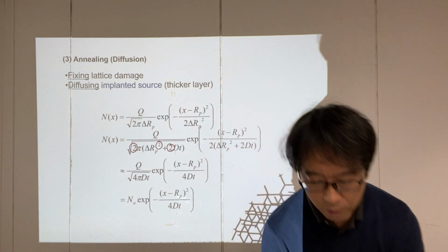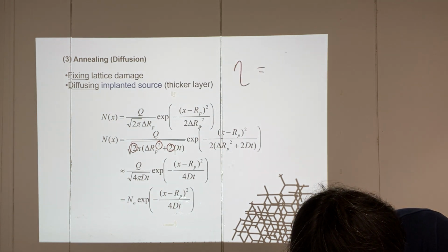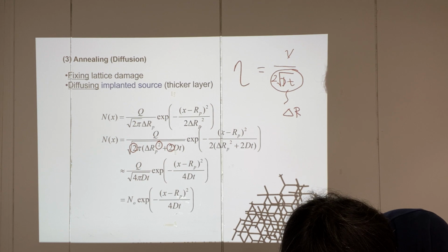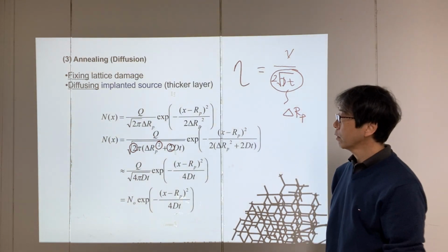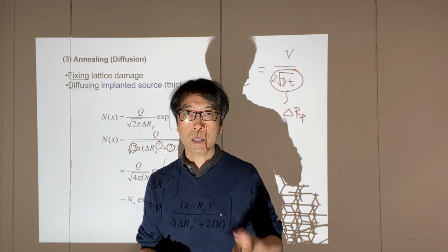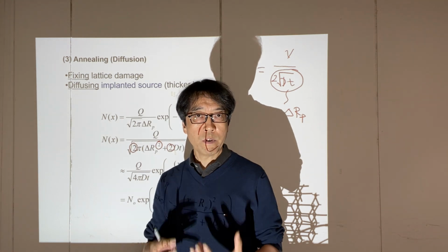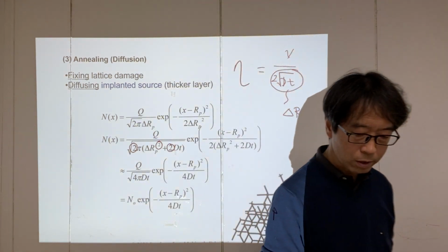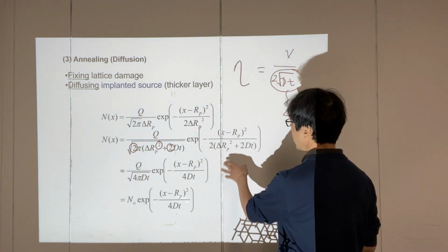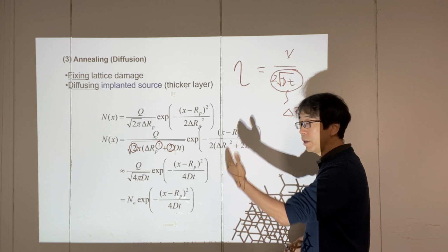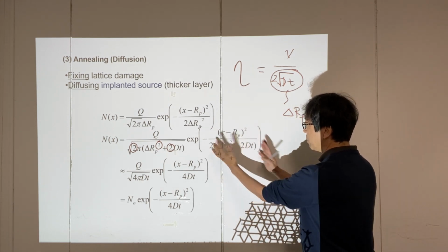Last time, remember, we used eta equals x over 2 square root Dt. So this is comparable to delta Rp. That's what I'm saying. Okay. So our model for solving the partial differential equation by introducing the similarity variable gives us very important meaning of the physics that's occurring throughout this process. And again, Rp and delta Rp will not change, right?